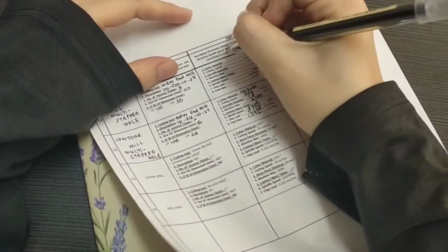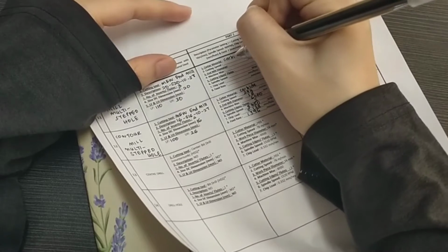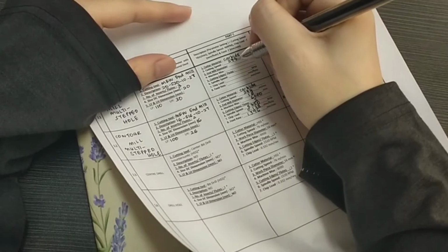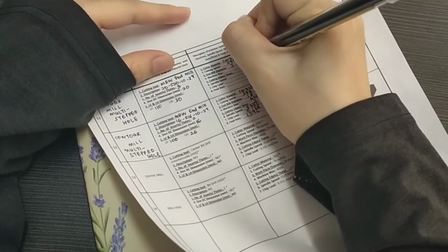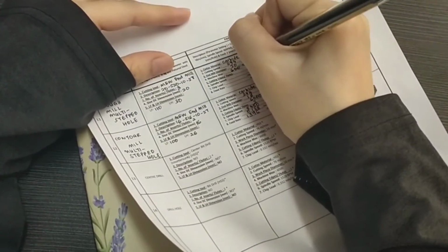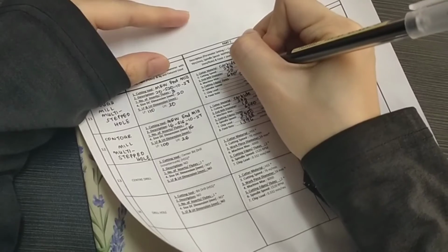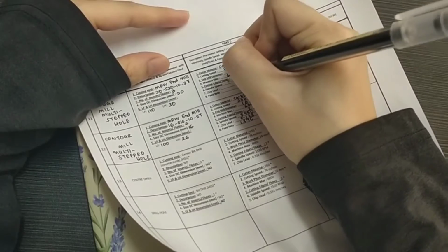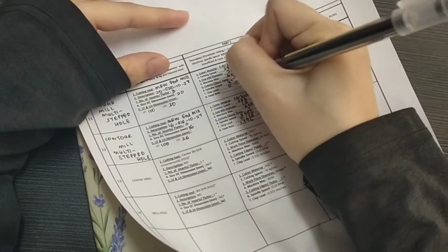Okay, so the cutter material, as usual, we use the carbide. And then for the cutting speed, that is given, which is 274. And then n millimeter is the same with the size DC dimension. I'm going to put 20. And then machine max, as usual, 6000. And then cutting edge and flutes is the same with the number of inserts and flutes, which is 3. And then spindle speed is 4360. And then the chip load is also already given 0.16.